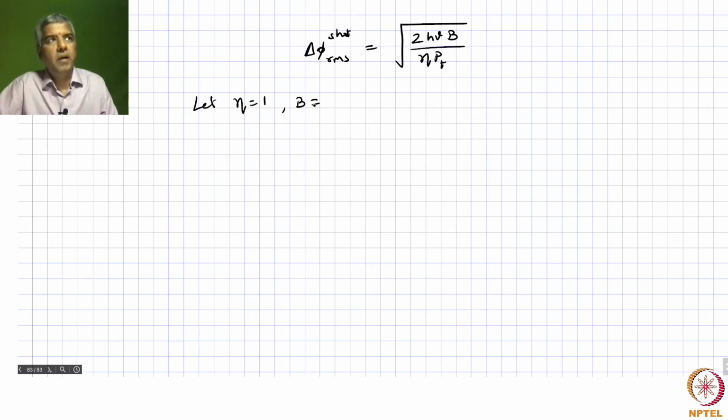What should be the bandwidth of your receiver? Well, we talked about using a phase generated carrier, and there we talked about something in the order of 500 kilohertz for this 200 meter coil that we had for the gyroscope. So you would say that yes, the receiver bandwidth has to be at least 500 kilohertz, so that you can pick up those frequencies.